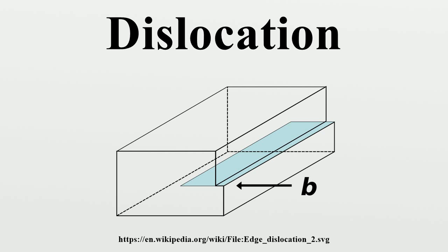If the cut only goes part way through the crystal, and then slipped, the boundary of the cut is a screw dislocation. It comprises a structure in which a helical path is traced around the linear defect by the atomic planes in the crystal lattice. Perhaps the closest analogy is a spiral sliced ham. In pure screw dislocations, the Burgers vector is parallel to the line direction.